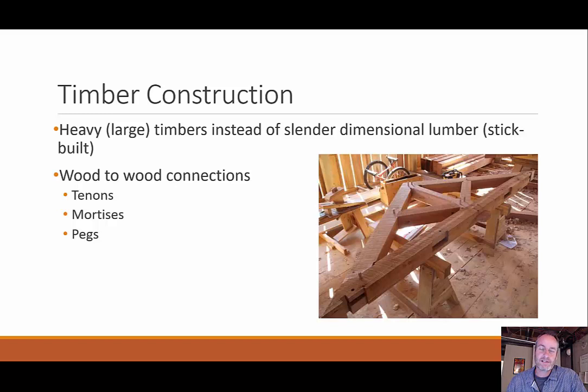Last time what we talked about was stick-built construction, where we saw those structures with all the 2x sticking up at 16-inch on centers, and you just see a lot of skinnier lumber spaced close together. Timber construction uses big, heavy pieces of lumber spread far apart. You can see an example of a truss here, these really big members, along with these little connectors.